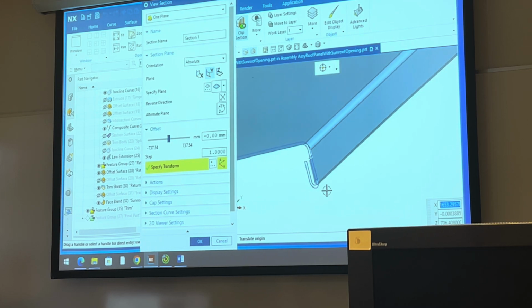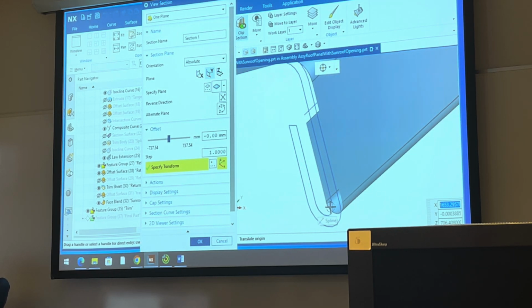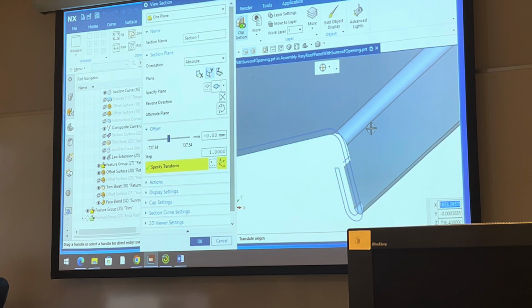That's what a sunroof opening is. This whole project, two weeks, all it was was this return flange, a fillet, the main wall, and a fillet. Everything we did was just to make that, all based on the weather strip, deflection, radius failures, and all those other things. A lot of work for just some little simple shape, right? But that's the real world.